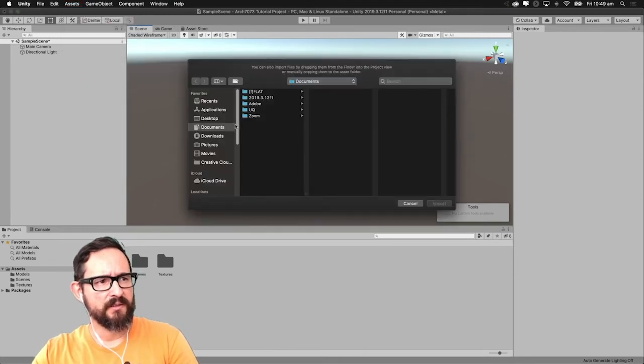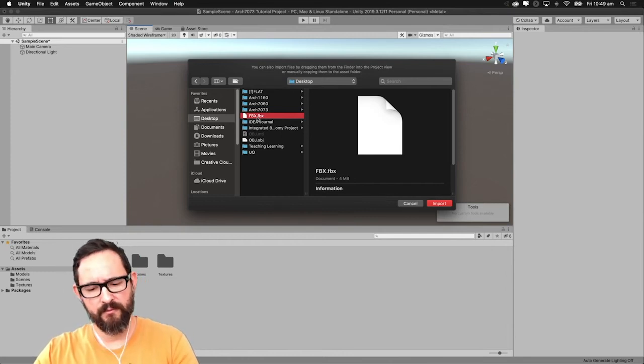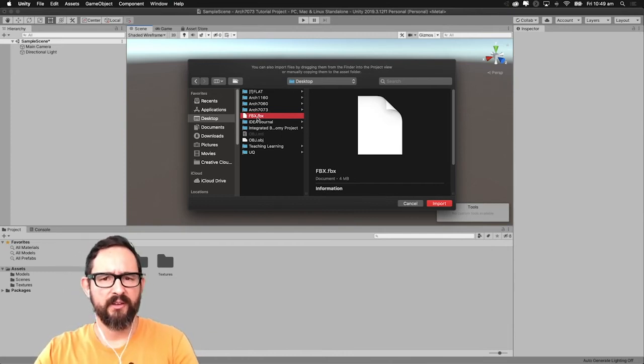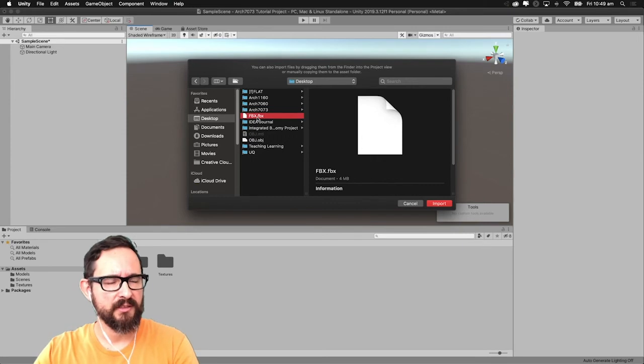And in this case, that's how we import the model. So we go to Desktop, and what I'm going to look at is the FBX. All software, Rhino, ArchiCAD, and Revit, they all export in FBX format. It's called MotionBuilder, but that's the exchange format. So also 3ds Max and Maya. So it's a general common format for animations, and that's what we're actually going to use, not OBJs.